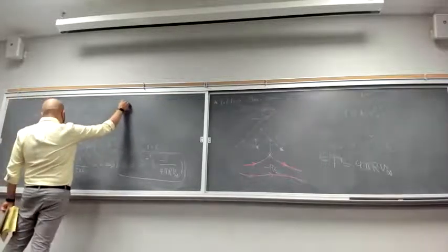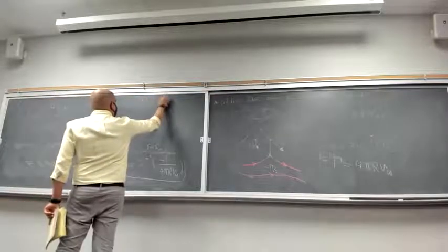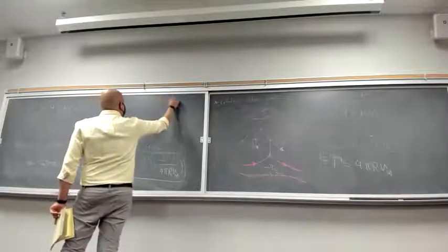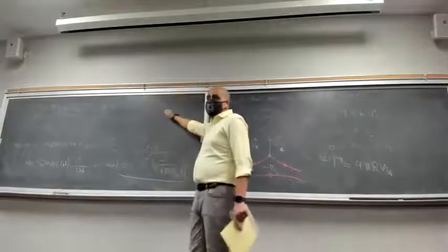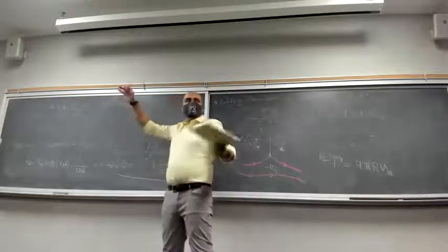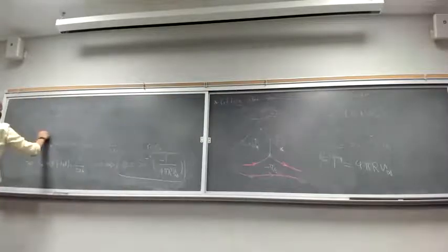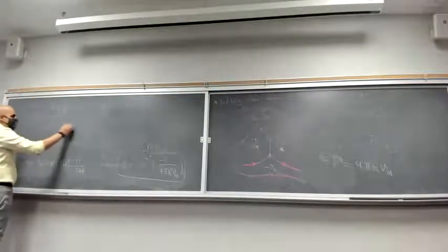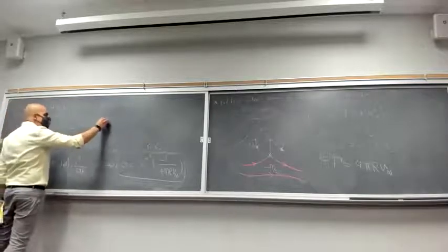It was V infinity cosine theta times 1 minus R squared over r squared, right? We want this to be 0. There were two conditions. Either r is equal to R, or theta is positive or negative pi over 2, right?